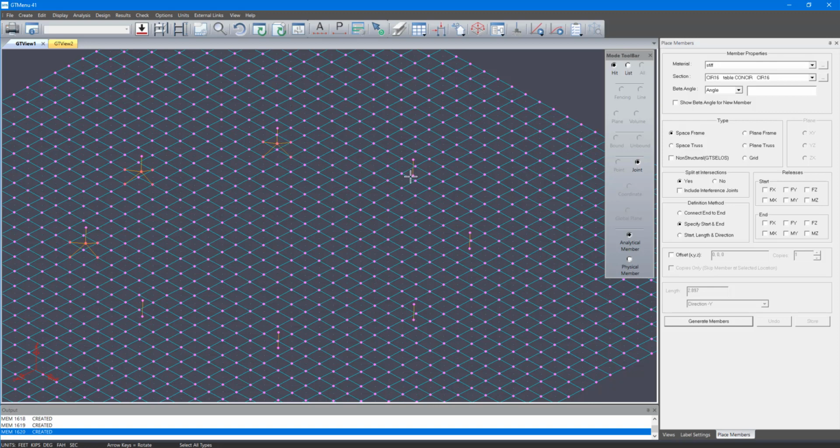If you have it going through a point, it's like a needle piercing through a piece of paper, and you will actually see very high stress concentration at the location where the pedestal actually meets the slab, okay? So this will go in and actually distribute it nicely, so your slab is not designed too conservatively, okay? Okay, so this is a little bit of work, okay, but we're almost done. As you can see, I'm on my last pedestal. You can come up with some creative ways to automate the drawing of these pedestals. Okay, again, this is not an exact science. It is finite element analysis, and it's an approximation to the actual site conditions.